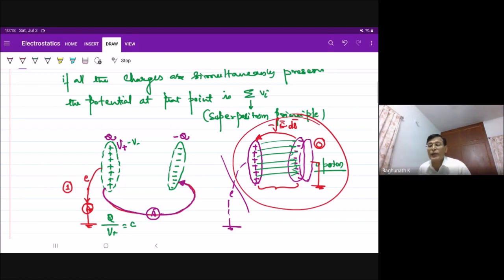When you touch it, you will experience a shock because of it. Power equipment will have a 3-pin plug in which one pin is earth, and that earth is connected to the body of the equipment. Because the earth is connected to the body, the body will always be at zero potential. Standing on the ground, if we touch it, there is no potential difference, because of which we will not experience the shock.